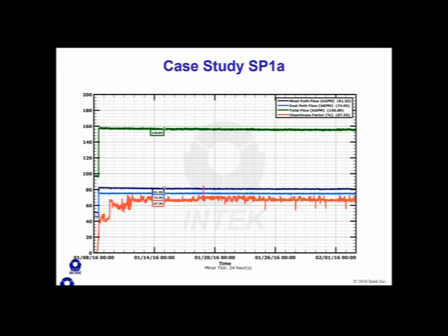And so they had an opportunity in January, just 2 months later, to go in and clean it. And so they did. They went in, they got rid of the debris that was pushed into the water boxes. They took out tons of gravel. And so then they came back up online after their New Year's outage. And you can see here the cooling water flow rate is at the design value of 156,000 gallons per minute. The east and west cooling water flow rates are very nice and steady. And we've returned to the unit's historically best cleanliness factor of 67%. Again, this unit has a lot more issues, but at least the cooling water issue was solved here.